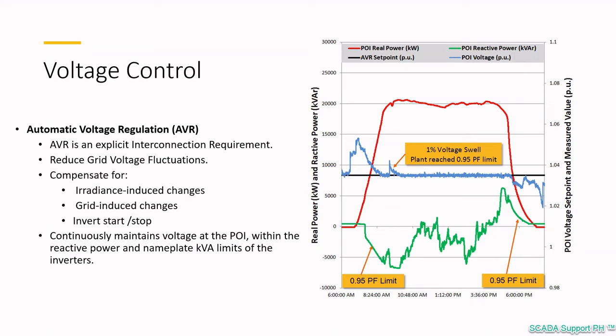In this example on the right, which is for a solar PV power plant in California, the system has the capability of producing a net power factor of 0.95 lagging at the point of interconnect when voltage levels are between 0.9 and 1.0 per unit, and absorbing a net power factor of 0.95 leading at the POI when levels are between 1.0 and 1.1 per unit while the generating facility is at maximum real power output.